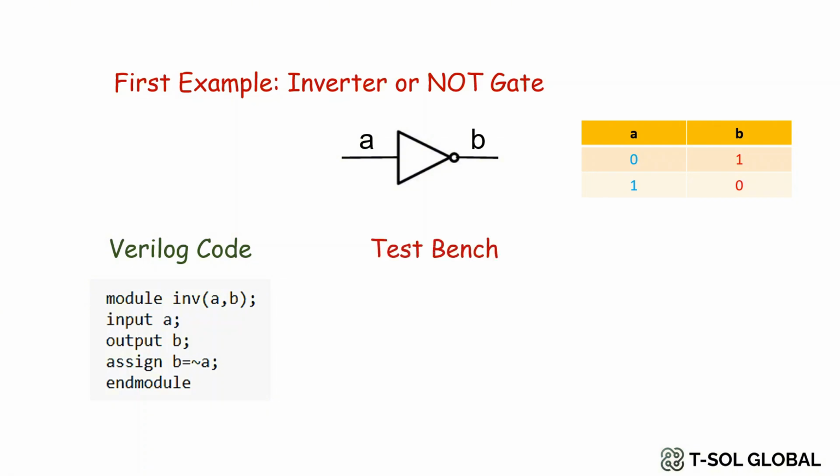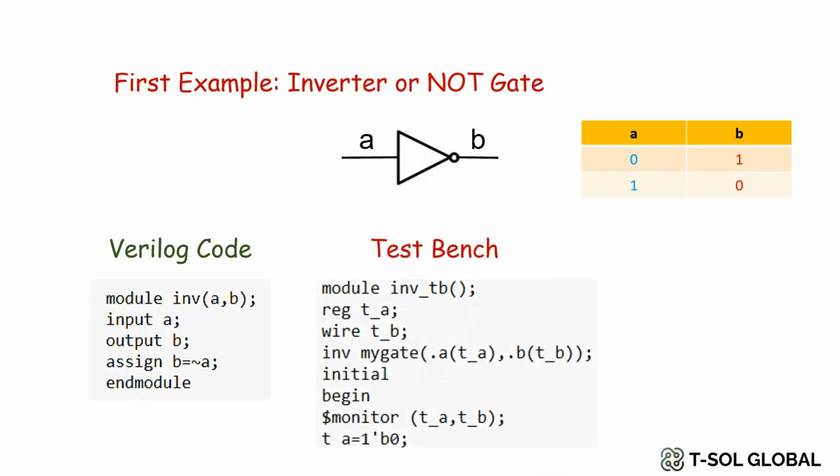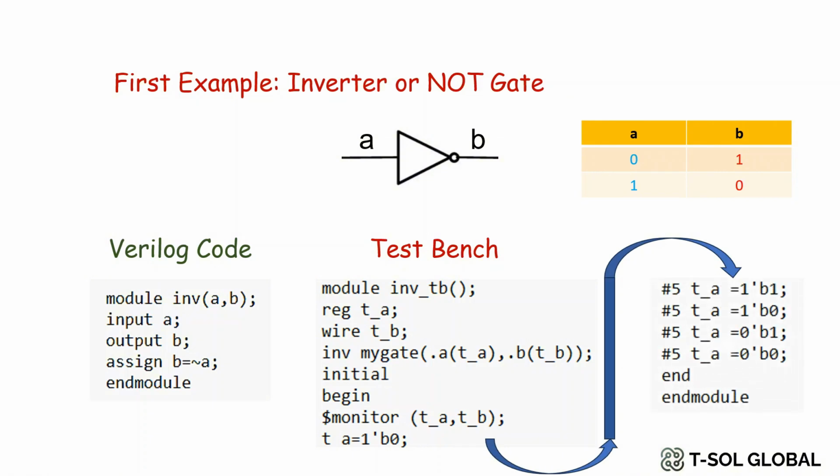You can also see the test bench for the inverter. A test bench is mainly used for testing logic. A test bench mostly uses logic which is not synthesizable. In the inverter test bench, you can see again we defined the input as a register and the output as a wire, and then we just map this with the real Verilog code and we put some timestamps so that the simulation can understand where it will change state. As I said, we'll have more explanation of this kind of test bench and Verilog code in our next few videos.